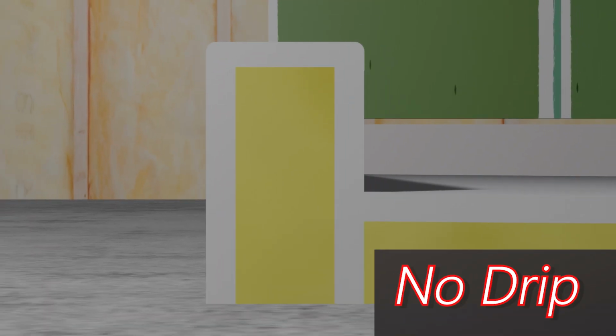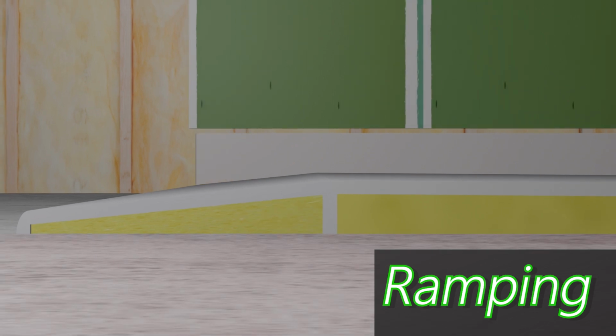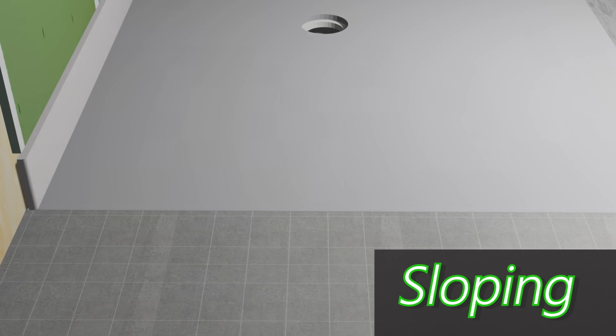No drip entry, drip entry, and ramping entry are designed to be installed floor level. Sloping entry is designed to be installed into a recess. A base with a barrier entry point could be installed into a recess, but you would need to remember that depending upon the depth of the recess, that would affect the height of your outer entry point.